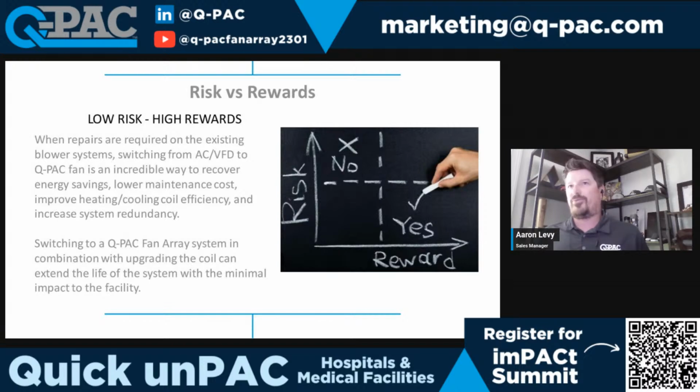The MTBF, so mean time between failure, which really gets you into about the 50% range, tends to be 100 to 125,000 hour range. So somewhere between, when you're looking at the L10, 6 to 10 years. And as Q-PAC gives you a 5-year warranty, we're kind of in that range of the lifespan of that system, even for a 10% field failure. We've got it covered.